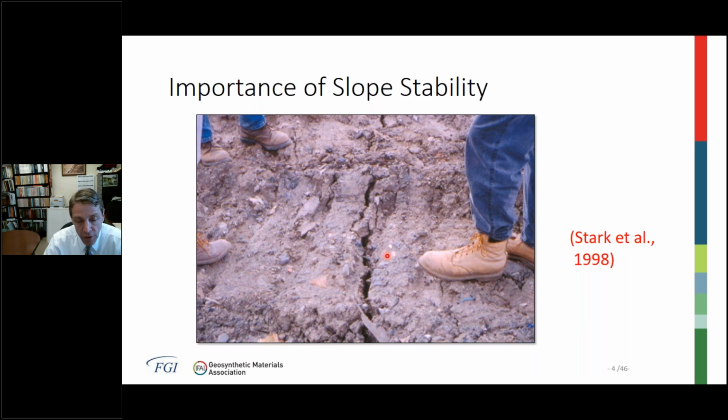So what should you do if you think it is a tension crack? You can put a couple pieces of wood or surveying stakes across this, put a Sharpie mark across it, and see if it's moving and measure how much it's moving instead of covering it in. If it moves in a short period of time, it indicates a tension crack. Now, that's all the good news. The bad news is, even with small tension cracks on the surface, that means there's significant movement in the liner system and probably damage to the geosynthetics in the liner system.